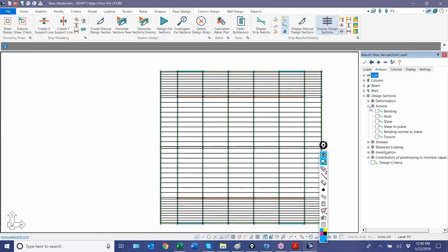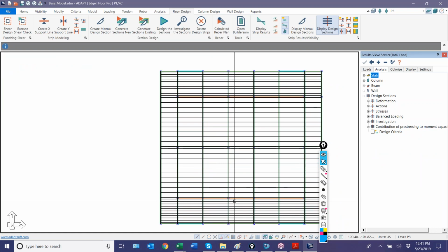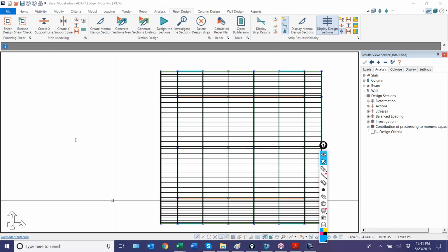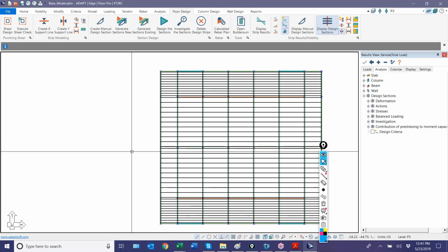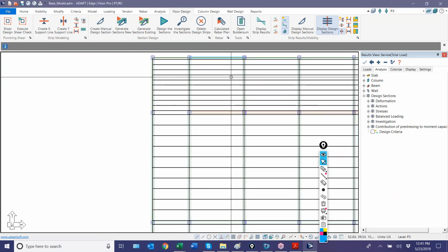Okay, ultimately we want to check for the PT design of these members. First we'll check precompression. We want to make sure we meet the precompression required for the design. There's a question, are the moments, displacements, and I'm just going to read that, Marcos. The moments, displacements, etc. of the design section is the composite action. Yes, it is the composite action.